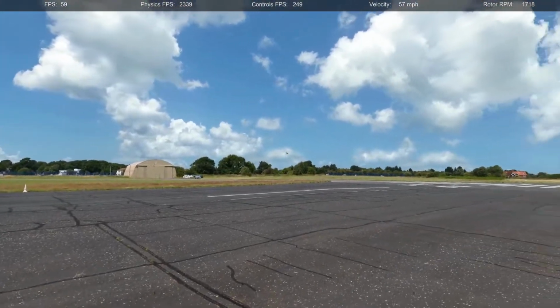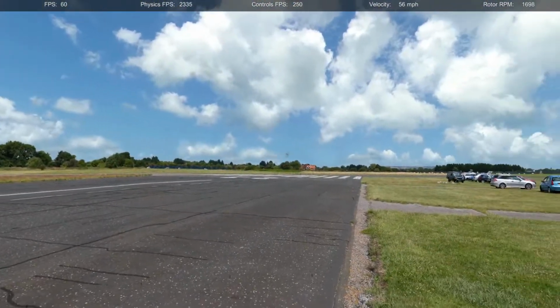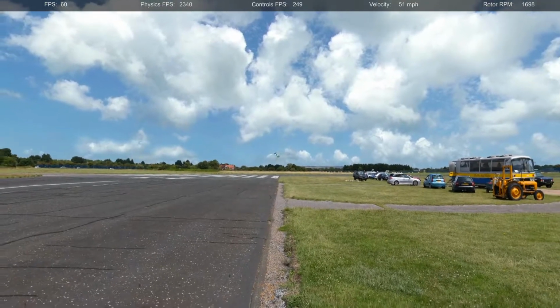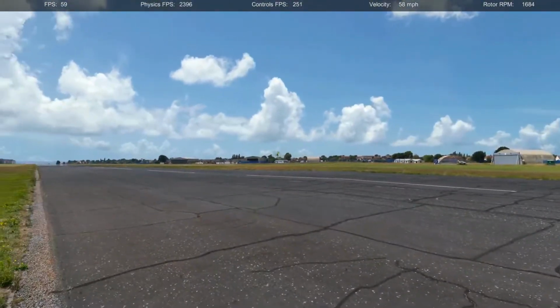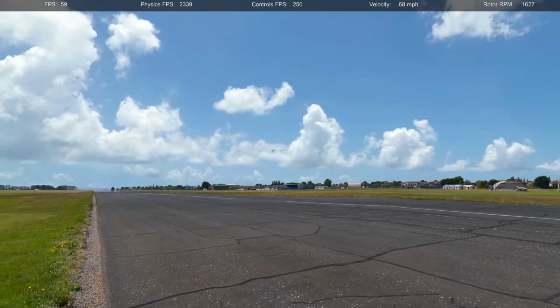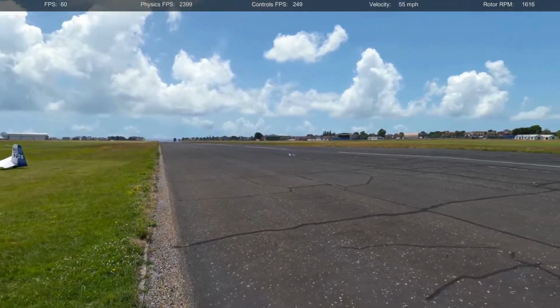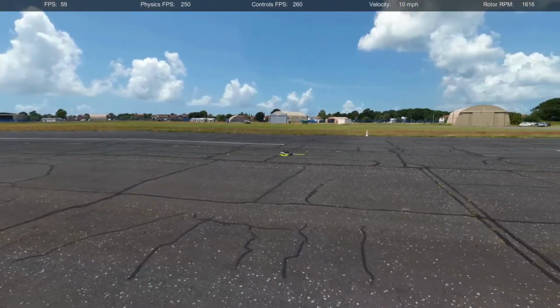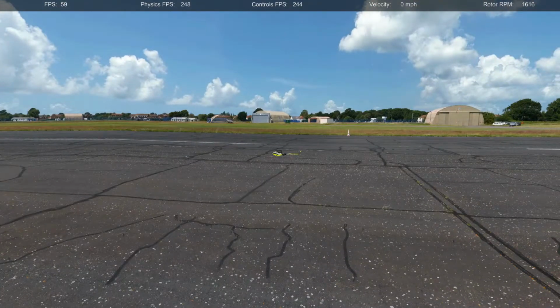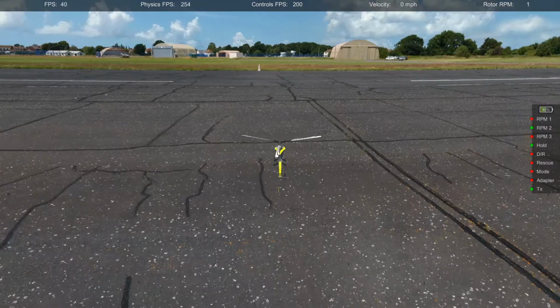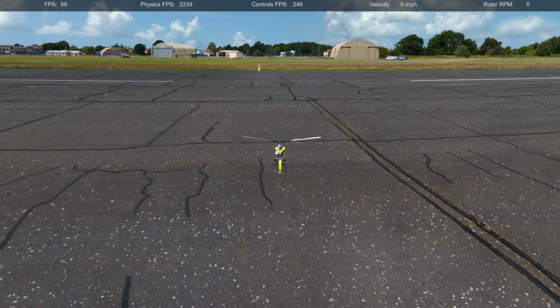So now I want you to imagine that you make the winglet really, really big. And in fact, you make it so big that it's 30% of the span of the wing. And then fold it out flat. Now you want to put the entire aileron control surface on the winglet. None of it extends inboard. Now, I just told you that there's thrust on this winglet, and that's because it rotates the lift vector forward.